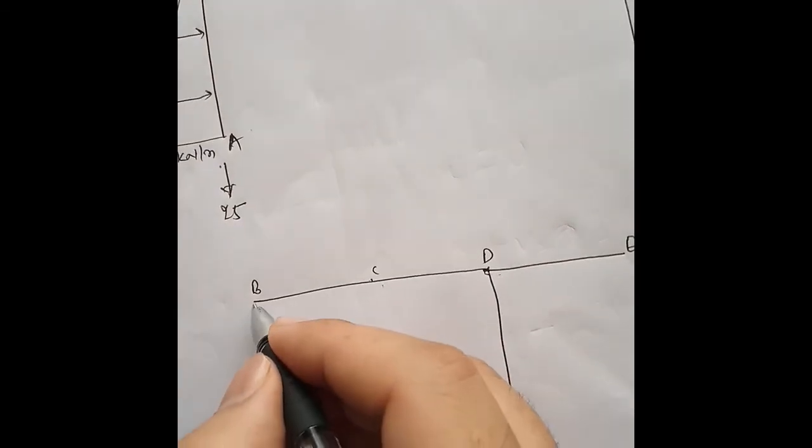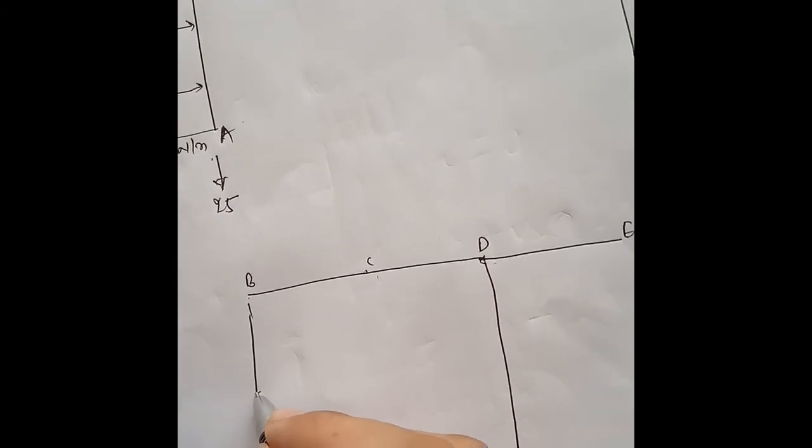Here we have determined that at x equals 4 at this section you have 210 bending moment. So let us suppose that 210 is here, and at x equals 3.055 from this B, we have the bending moment of 215.64. So we will locate this 215.64 here.